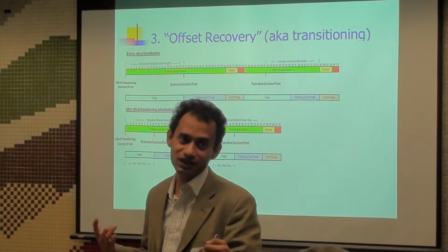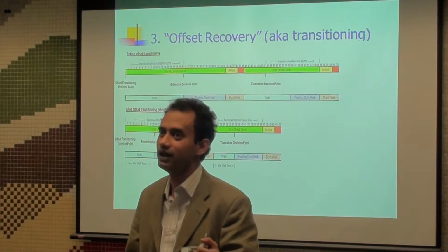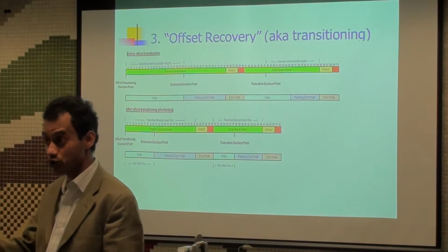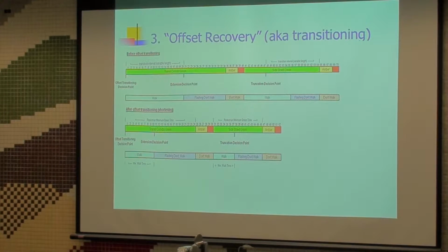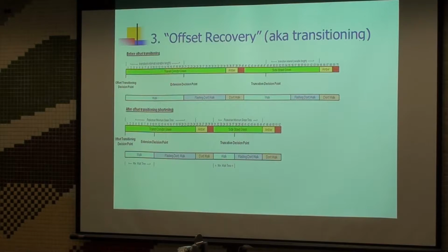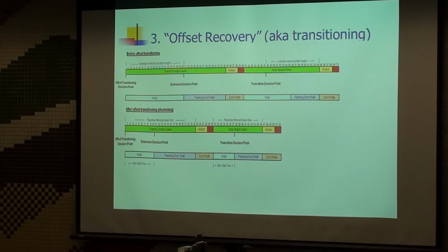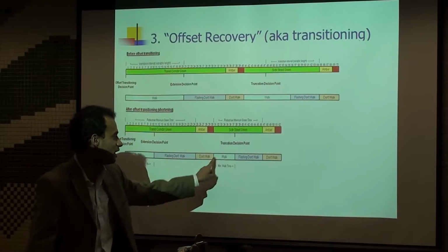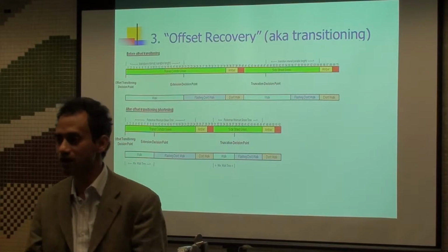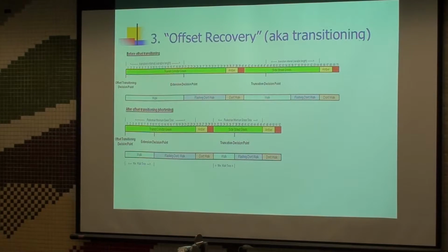That's why we need really careful consideration of how much delay or queues we can afford to develop when we are offering this kind of extension, particularly for the side streets. That's one thing. The basic principle is make sure you have minimum walk time. You must confirm that exists in your signal timing.